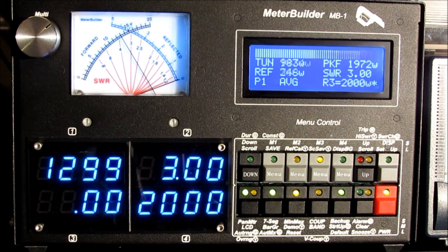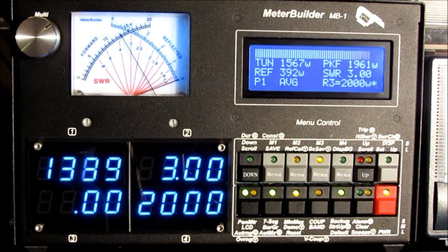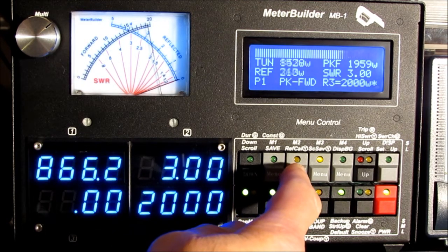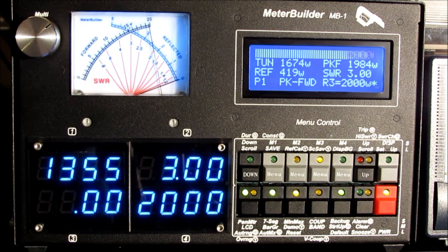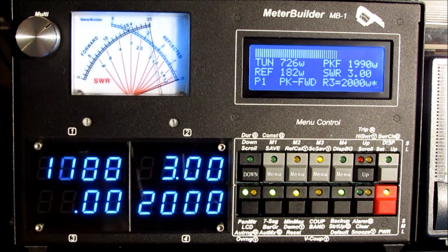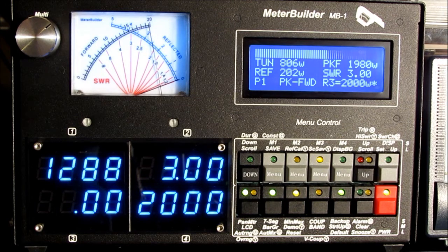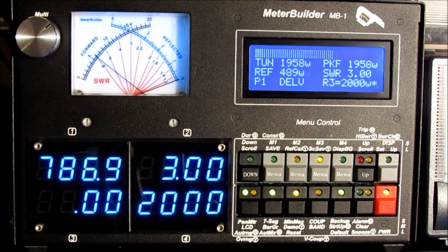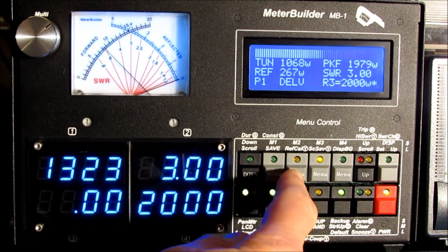When I select average, for all of the other readings you're going to see on the panel meter, only the forward needle applies. The reflected needle is used only in the tune mode. So you can see I have some averaging filtering going on there. Peak forward. Again, I'm in the 2000 watt full scale range, and I believe the peak hold is set to 1 or 2 seconds. So you can see based on the random value that the peak value is indeed what we expect it to be. Delivered real-time power, which is forward minus reflected.